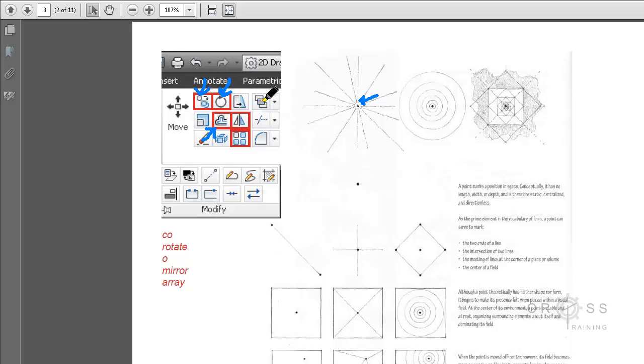And there's several other buttons going on here. So this one is kind of the trim button. You can also trim or extend a line. So say that you wanted this line only to come out this far, and you have an actual object, maybe this is edge of paving or something. You can click on this button here, which is the trim button, and then select the object you want to use as the cutter, and then press enter, and then select the object that you want to trim off, which would be this line extension over here.